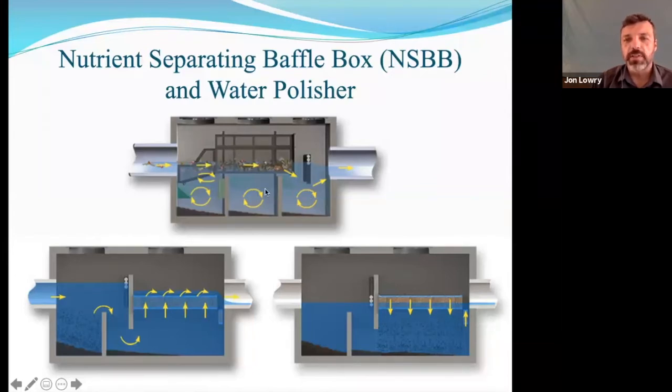And we definitely notice this when we do our cleanings, that we get a lot of gravel and coarse sediments in the first chamber, and by the time we get to the third chamber, it's a lot of sludge and really fine sediments. And then the other component of this device is that it has an oil boom system to collect floating greases and oils.